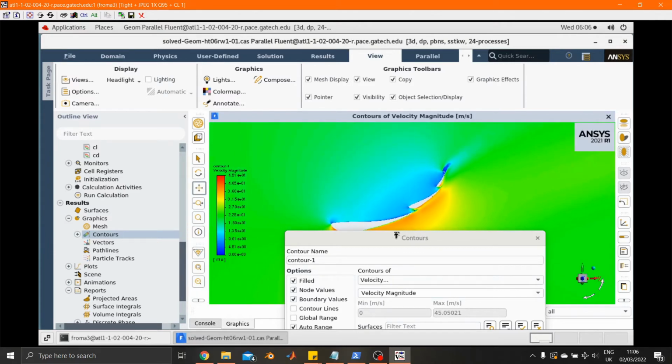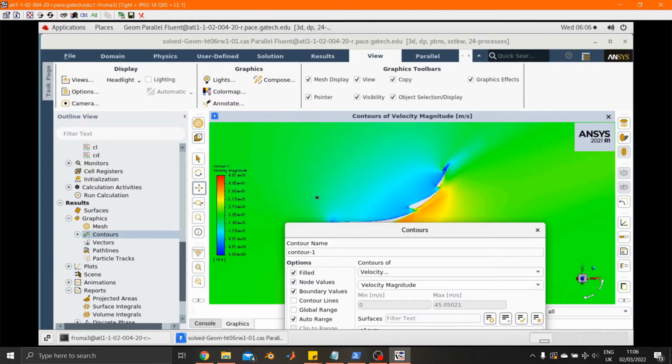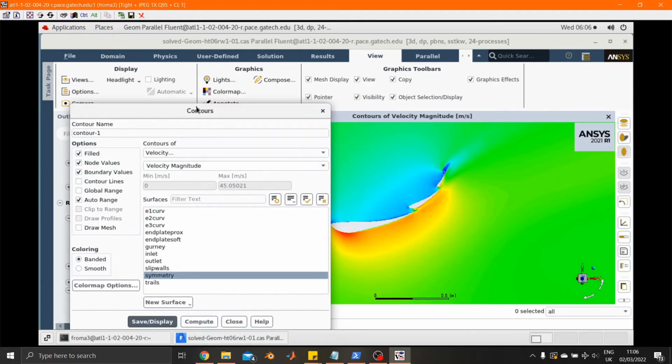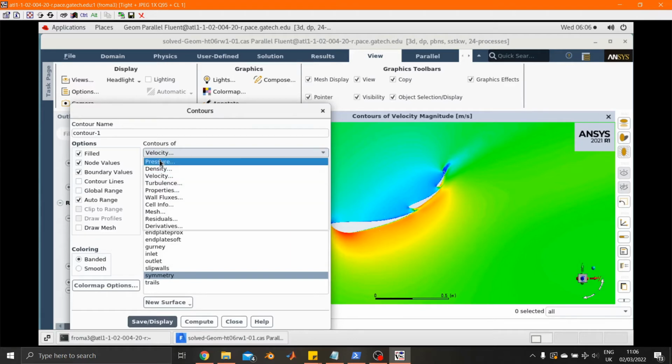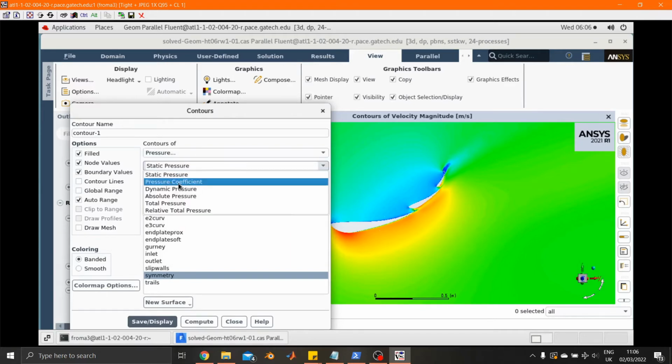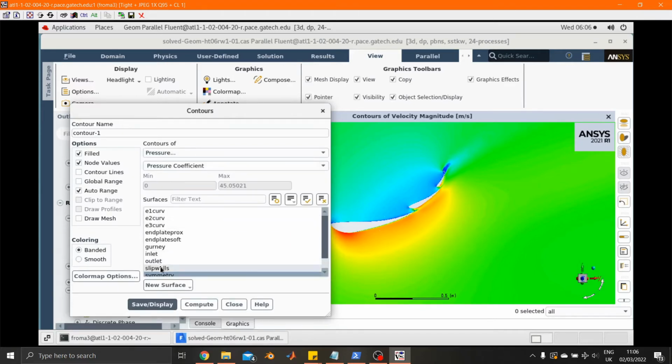Okay. So those are both flat contours. There's just a symmetry plane that we were painting with pretty colors. We can also check the pressure on the actual surface of the wing itself. So if we go back to pressure and pressure coefficient, instead of drawing it on the symmetry, if we untick symmetry, we can actually draw it on the rear wing itself.